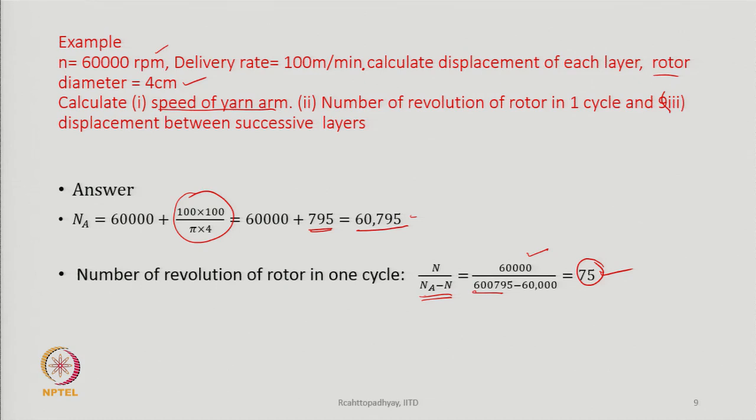But whenever there is a breakage of the yarn and we start the process, there will be a thick place created. So, every rotor break means as soon as we start the operation again, we feed the fibre first and then feed the seed yarn, and therefore the seed yarn end joins the fibre ring which is already formed, and that ring is of uniform thickness, but that thickness is not equal to the thickness of the yarn that we want to make.